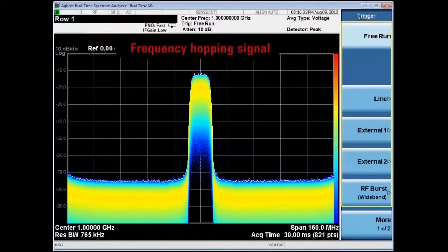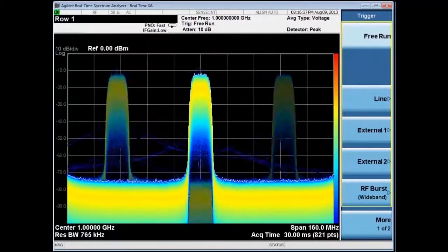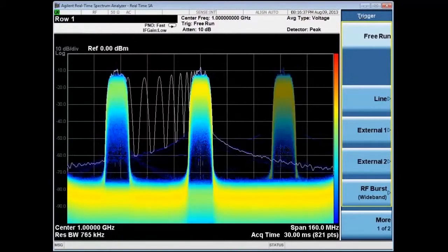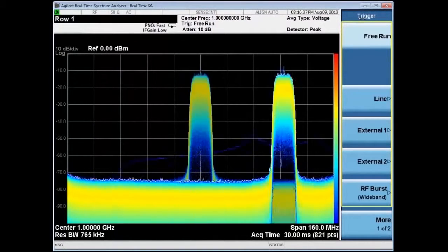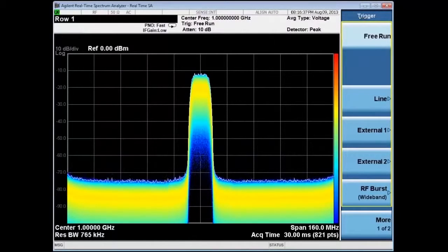Finally, let's take a quick look at the frequency hop signal and then dig deeper with some more analysis. If you wanted to understand as much as possible about a signal, a good approach would be to either use triggering or use a recording when triggering is not efficient. Most signal analyzers cannot record signals much greater than a few seconds at wider bandwidths.